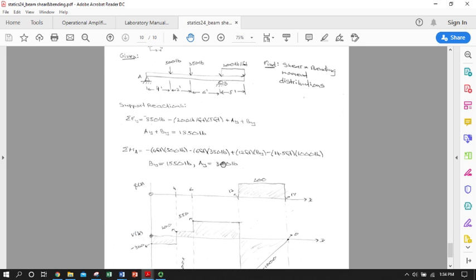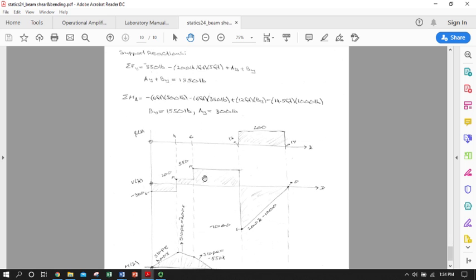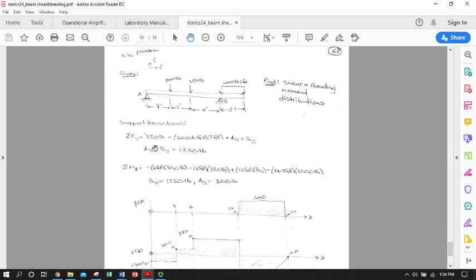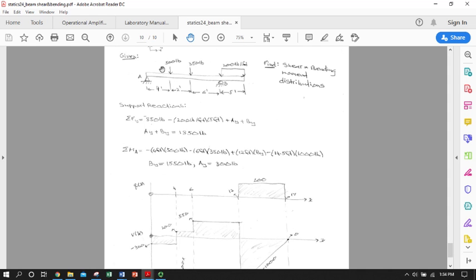So here it is. Now we're going to write graphically based on this plus what we know about the support reactions and the applied loads. We're just going to do in our heads what the shear force is. So if the support reaction is giving 300 pounds here, we know that all along here the shear force coming from the remainder of the beam has to be a negative 300 pounds. So we can draw a line at negative 300 pounds.